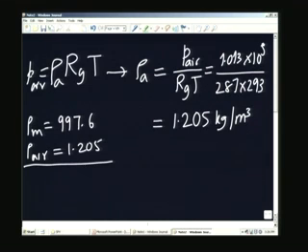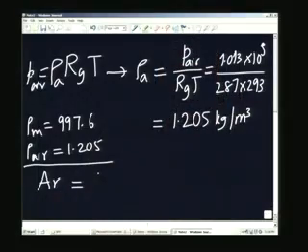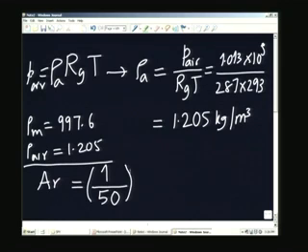The second part of the calculation requires two things. One is the area ratio. If you remember, the area ratio comes because we assume that the fluid, manometric fluid, is incompressible. Therefore, to determine how much is the change in the height of the liquid within the well itself, we have to use the area ratio. This is how it comes into the picture. This will be given by 1 millimeter diameter for the tube, and the diameter of the well is 55 centimeters. So, this will be proportional to the square of this, and this comes to 4 into 10 to the power of minus 4. There is no dimension because it is the ratio of two areas.